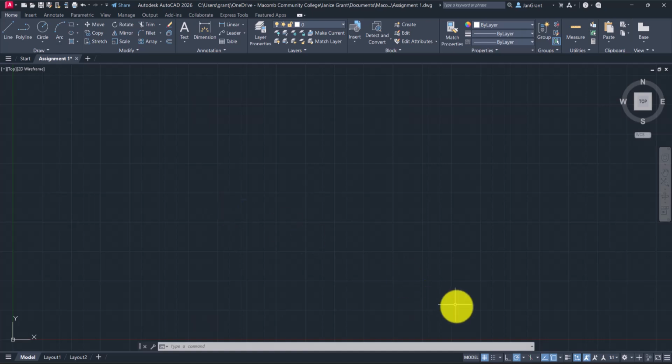At the bottom right, we'll have several tools that we can use. The ones that are blue are on by default, and the ones that are not blue, like gray, are not on, and we'll be working with several of those as well. For example, that very first icon, not the model, because we're in the model, but the first icon that says Display Drawing Grid: if you click on it, the grid is turned off, and if you click on it again, the icon will be blue, and the grid comes back into your drawing.